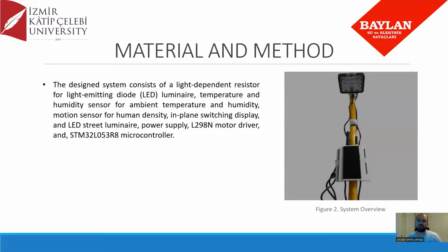The microcontroller used in the embedded system is programmed with the C programming language to enable the communication of the sensors and data transmission. It also consists of a LoRaWAN device, LoRa gateway, server, and application that enables the system to exchange information, retrieve information such as time and date, display broadcast information, and store sensor data. Voltage control on the motor driver is done by pulse width modulation.